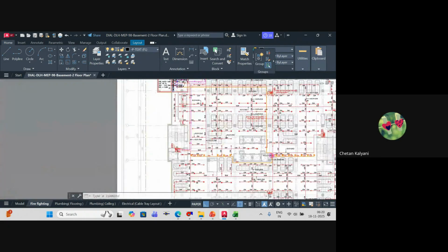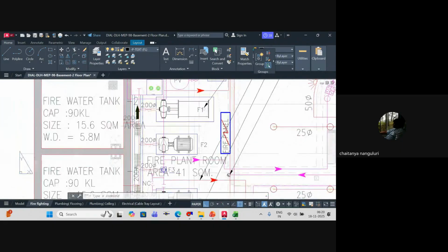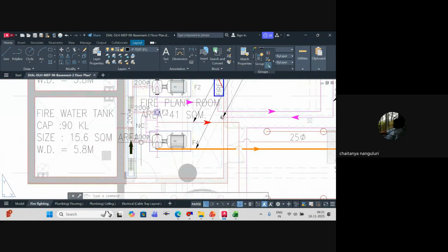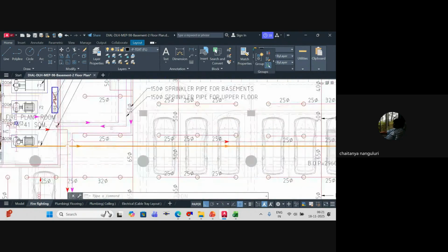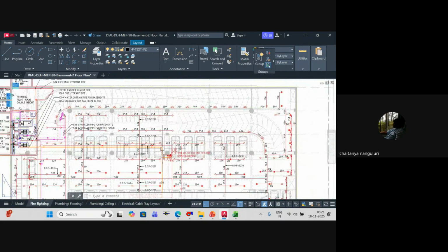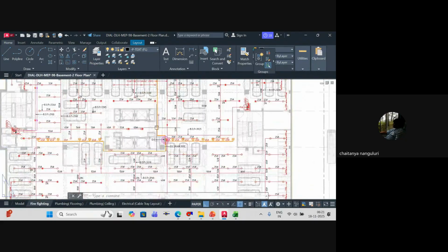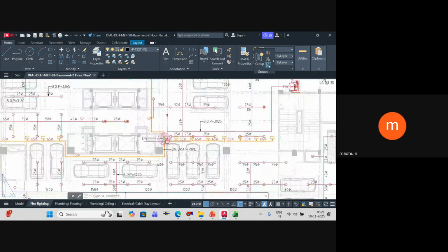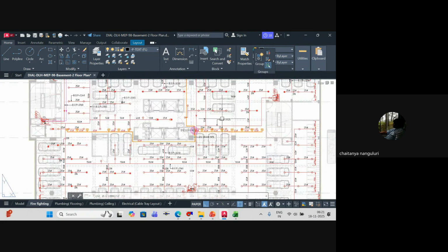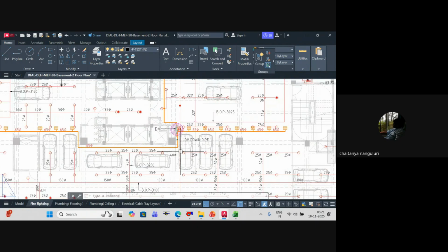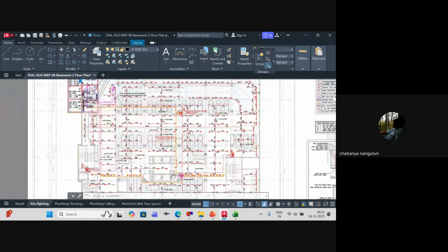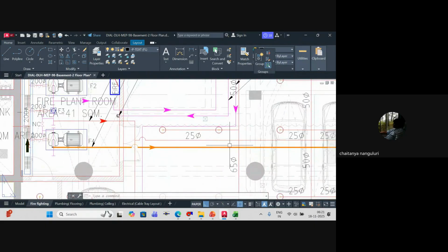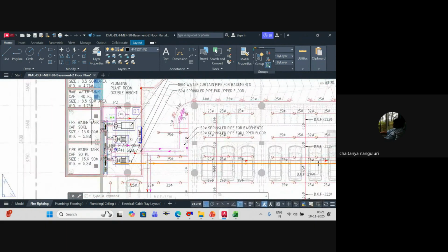If you see it here, this is a separate pump. So we have a common suction manifold. From the suction manifold, you have a water curtain pump, and from the water curtain pump, a separate line is going. You can see the orange color one, right? From this, it is splitting to the left and right side. Am I clear? Like this, you basically design your water curtain system. So you'll have a separate pump, but the tank volumes you could basically add together. Clear?